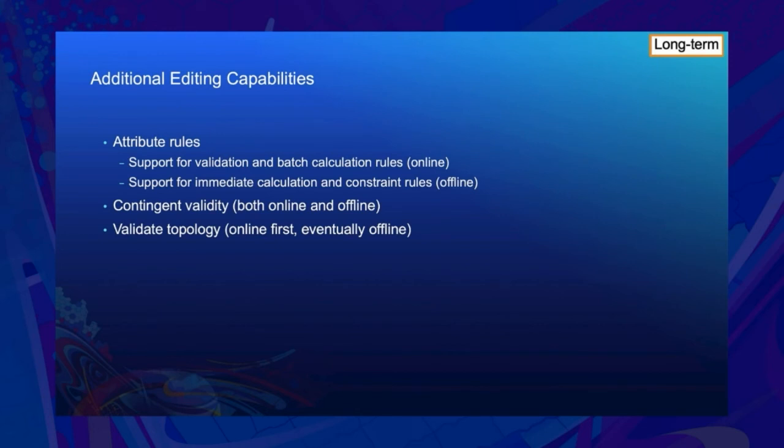The classic example I give is, so what it is, I guess I should say that first. What it is that the value of one field can control the value of other fields on the same feature. And the classic utility example is that you have a pole, and when the pole material is wood, the allowable values for the pole treatment type attribute are paint, none, or creosote. That's how you treat the pole, so it doesn't rot. Now, when the pole material is set to steel, the allowable values for the treatment type become none and painted, because you can't put creosote on a metal pole.